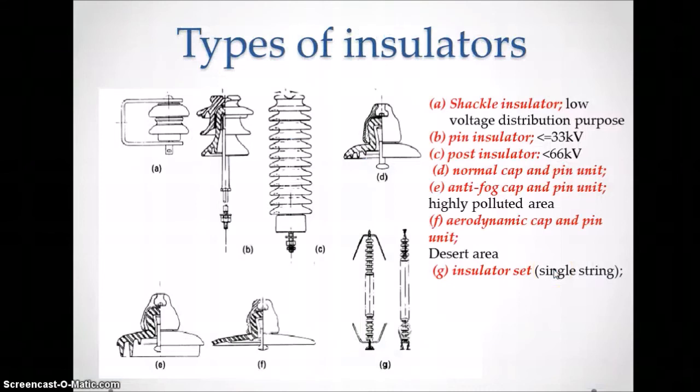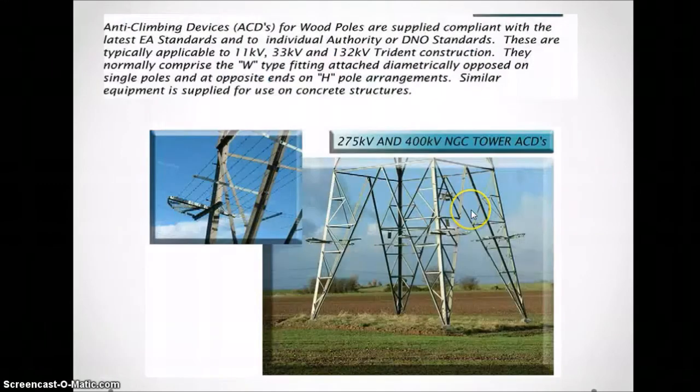Insulator, so we can choose the type of insulator. We have seen the insulator is to provide insulation as well as isolation. We can go for shackle, pin, post, normal cap. Well, it depends upon the area or voltage. We can choose what type of insulators we need.